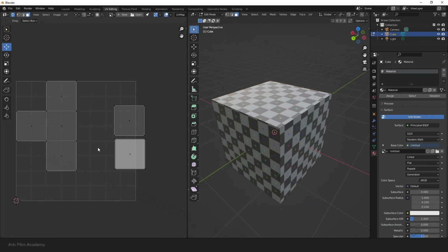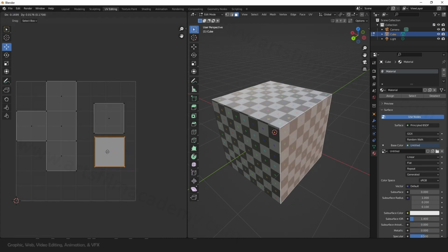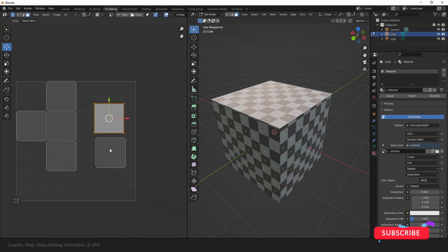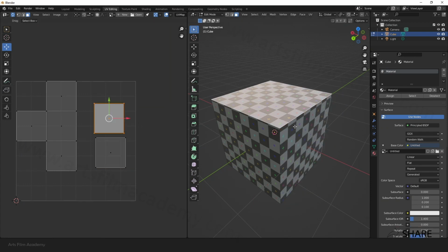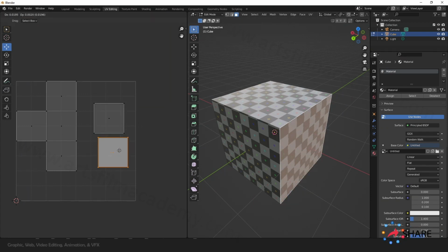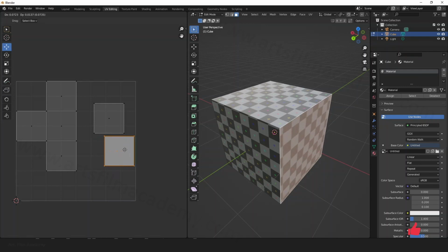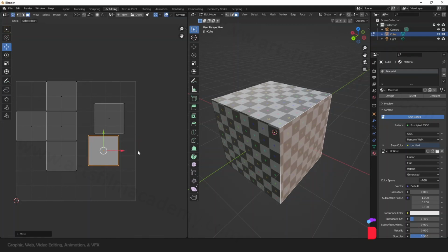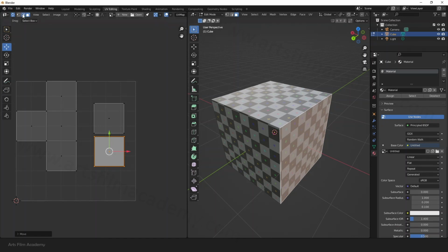Now let's come back to this mode, and you can see now we got these two. Now we need to identify whether these edges are in the proper position. So you can see if I move this, both are not stitched together, so it is very difficult to continue. So we need to position it perfectly. So I'll go for edge mode, and let's identify where this edge is.